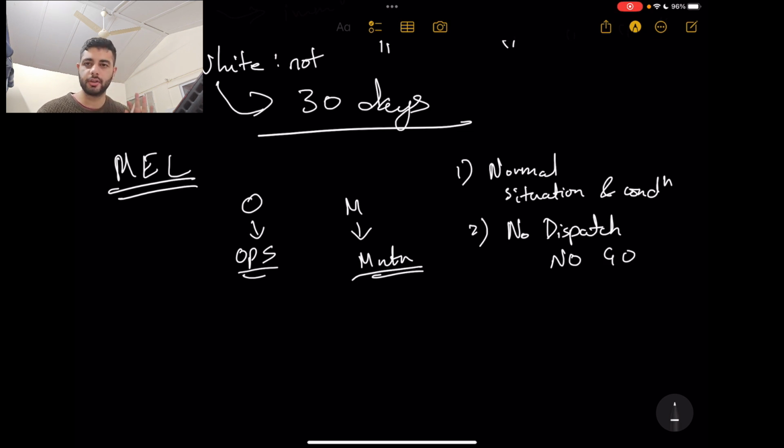Okay, no-go with this particular system faulty. Third one is not related to MEL. Example is I've put takeoff thrust, but my parking brake is on. It's not related to MEL. The operations should know that, oh my god, I've left the parking brake on. It's a stupid mistake. People do make it.